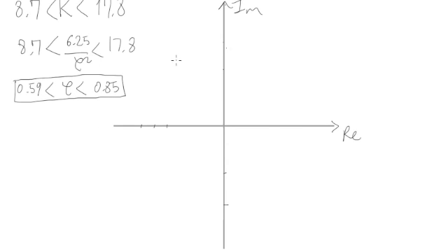Okay, so on the imaginary axis, if we have a pole here, so this must be a straight line, the damping ratio of this pole corresponding system, obviously there is a complex conjugate, but the sine of this angle, the sine theta, gives me the damping ratio. So in other words, this angle here is the arc sine of the damping ratio that I want. From these values, I can relate that this angle here must be larger than 36 degrees and 58 degrees. I find these angle values from this relationship. So a pole here has a damping ratio that is graphically the sine of the angle that this pole makes with the imaginary axis. So that's an important point.